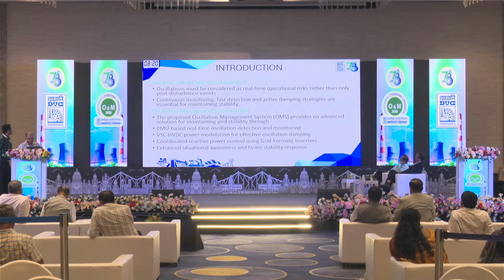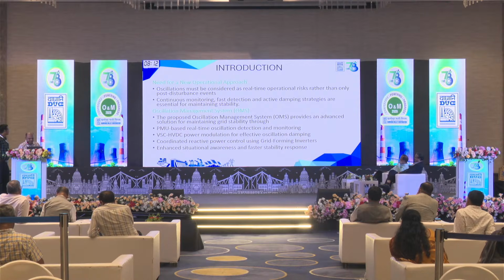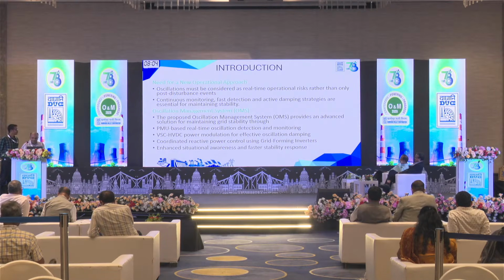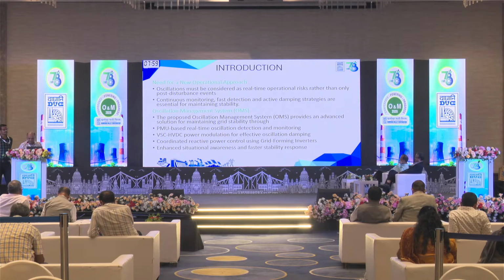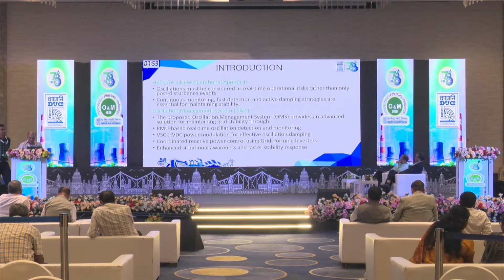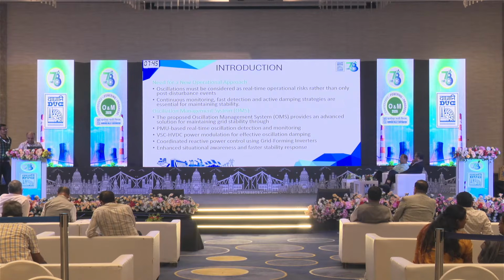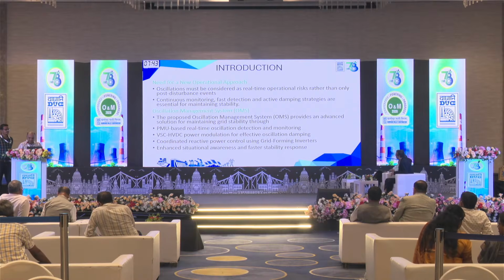Need for OMS. To manage this challenge, oscillation must be treated as a real-time operational risk. Continuous monitoring, fast detection, and active damping control are essential for stable grid operations. We therefore propose an oscillation management system combining PMU-based monitoring, HVDC modulation, coordinated reactive control, and grid-forming inverter support for a faster and more reliable stability response.